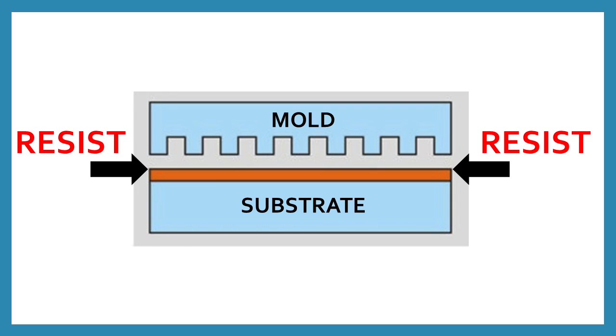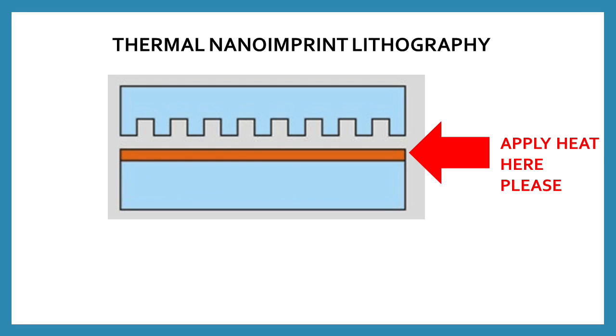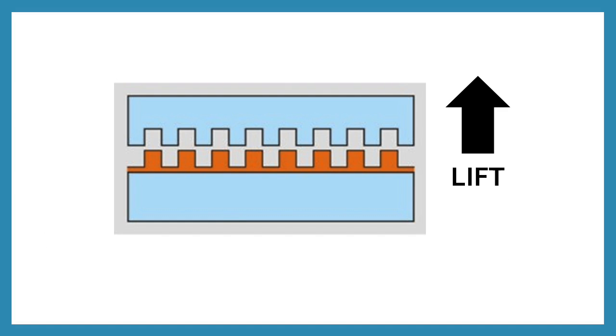Hey, I watched a documentary about this. Nano-imprint lithography is a simple process that uses a mold, which is a mask used to transfer a desired pattern, to emboss a resist, which is the material that receives the pattern. Particularly in thermal nano-imprint lithography, a thin film is pressed and heated between a pattern template and a substrate. Upon heating, the pattern film adheres only to the substrate.